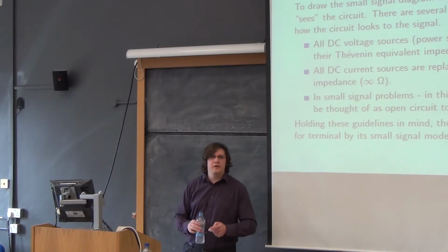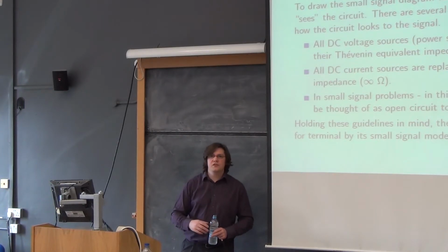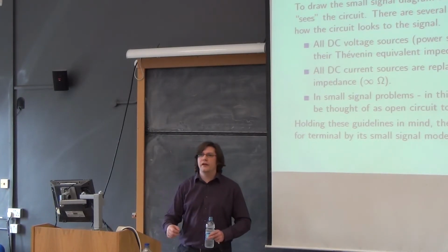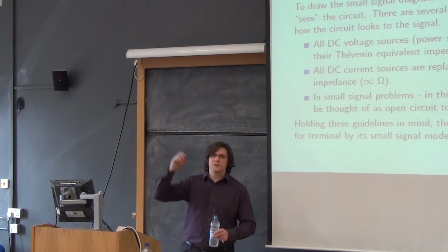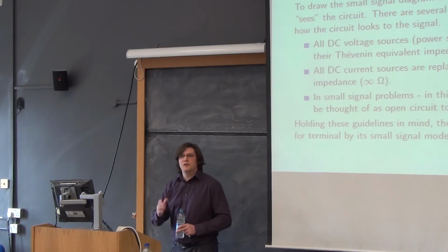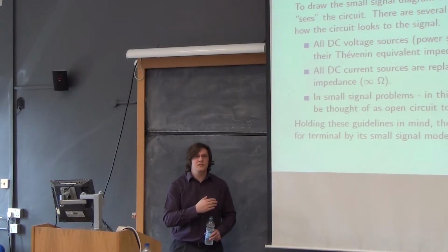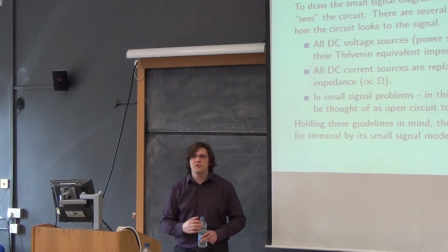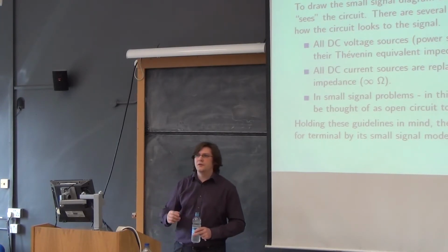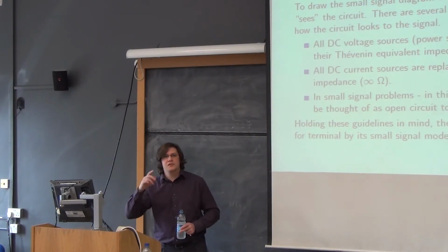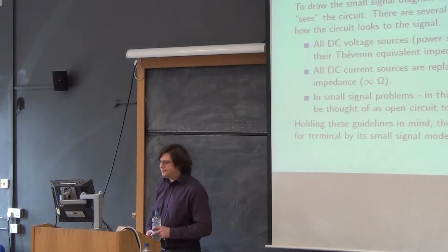And we were saying that there would be a 0.7 volt voltage source with a little resistor, RS, in series with it. And we said the value of that little resistor depended on how much DC current was flowing through the diode. And I drew a curve and I drew a tangent to the curve, and I said that RS varied according to the tangent of the curve, and so on and so forth. And then later on we did the same thing with transfer characteristics and transistors, where we had VB on X and IC on Y. And I said, well, the GM is dIC by dVB, and you put a tangent on it. Broadly the same sort of thing, just slightly rejigged.